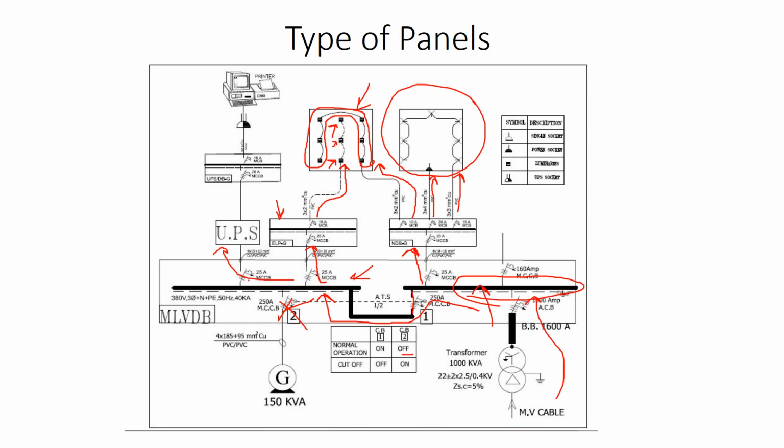Then the UPS itself is charged and at the same time supplies power to the UPS distribution board. Then it will be connected to the most important or critical equipment, such as the computers, because we would like it to keep running all the time, even if the electrical power fails, because they have important information.